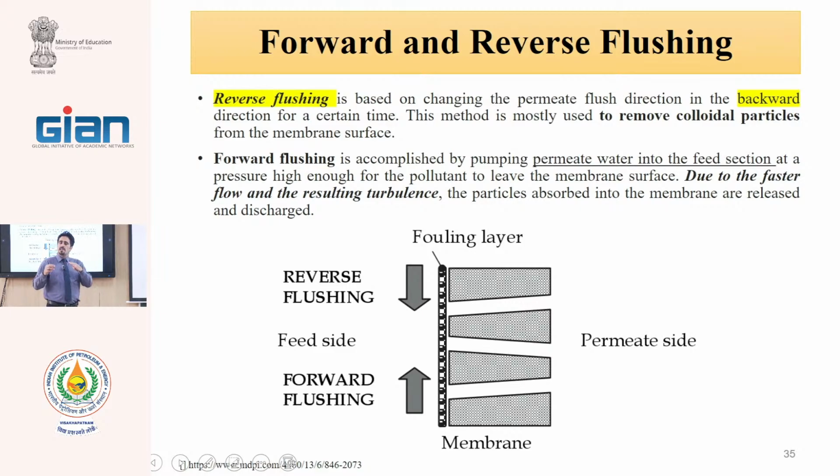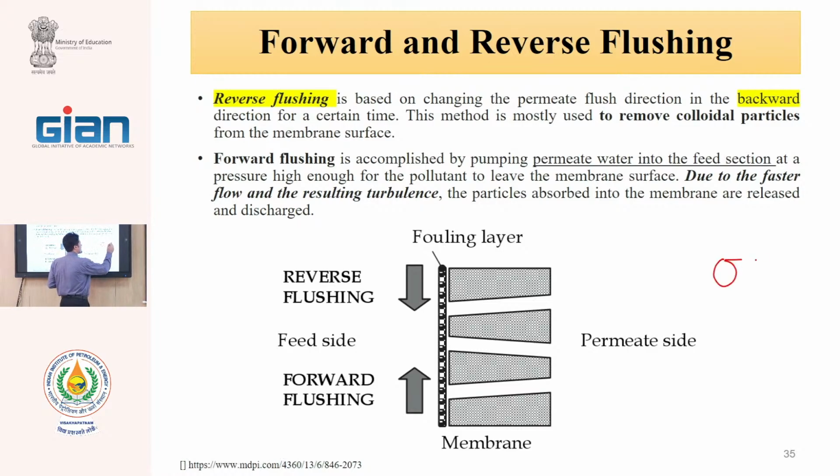In this case, instead of feed, we use water from the surface of the membrane, okay? In the forward flushing, our direction is similar to the feed. When we have this model, feed comes here, and here is the concentrate.